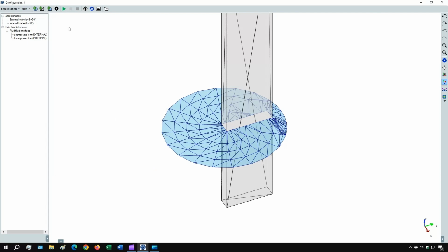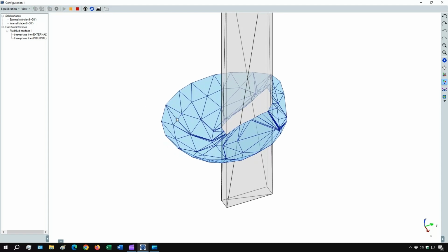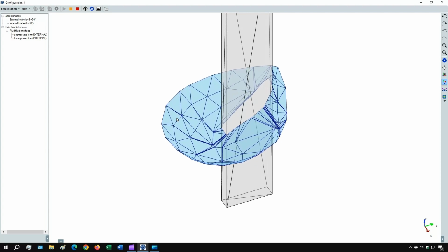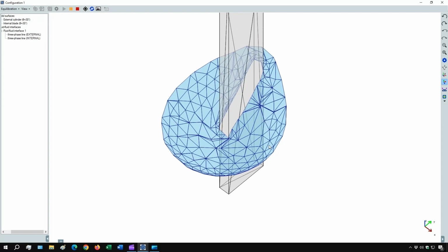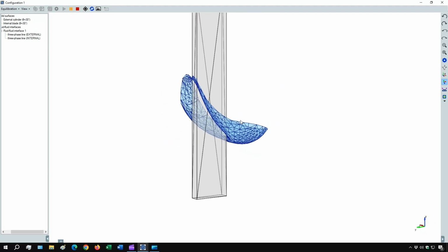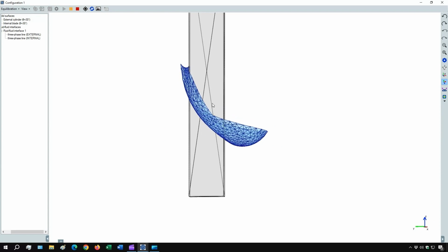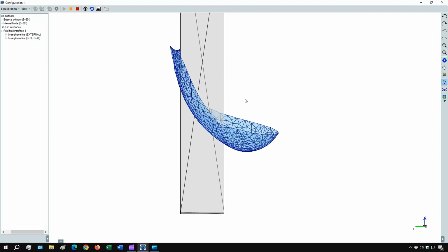If now we launch again the simulation, you will see that the mesh will maintain, for the whole simulation, a not too high refinement. And this will allow the simulation to evolve the mesh toward its equilibrium shape within a faster time. So we now wait until this not too refined mesh has reached its equilibrium shape. And this time, the simulation time to do so will be reasonable, thanks to the mesh being not too refined.